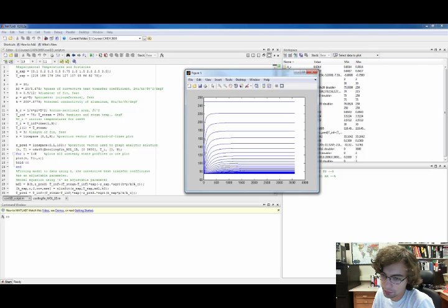The others down here don't approach nearly as high of a steady state temperature, and they approach that steady state slower, which is exactly what we expect. And so this is kind of the theoretical unsteady state startup temperature profile for the fin.